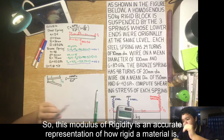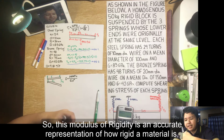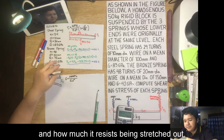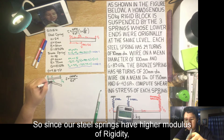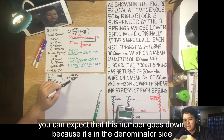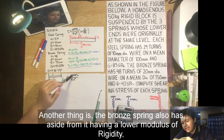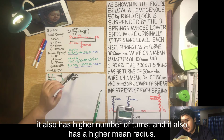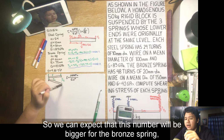So this modulus of rigidity is an accurate representation of how rigid a material is and how much it resists being stretched out. So since our steel springs have higher modulus of rigidity, you can expect that this number goes down because it's in the denominator side. Another thing is the bronze spring, aside from having lower modulus of rigidity, also has a higher number of turns, and it also has a higher mean radius. So we can expect that this number will be bigger for the bronze spring.